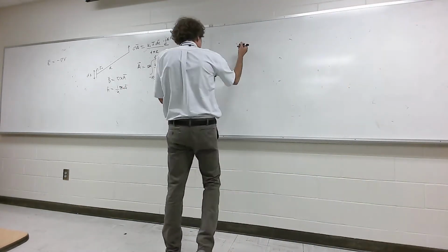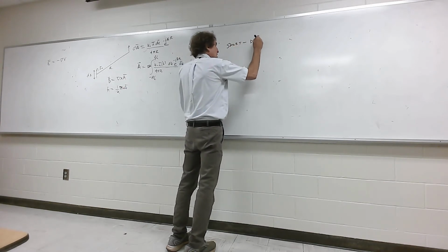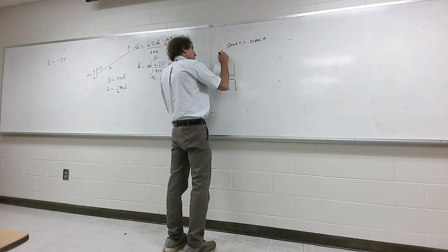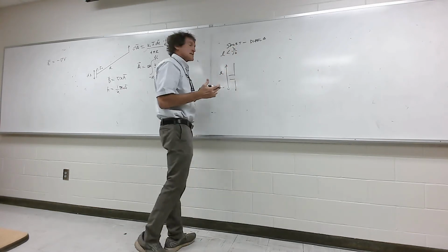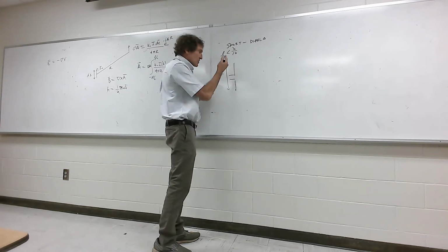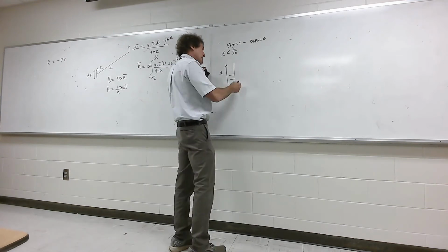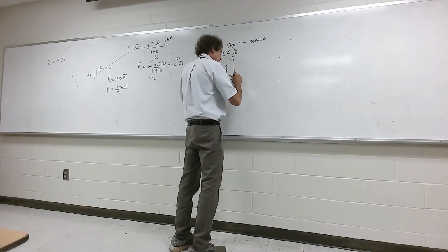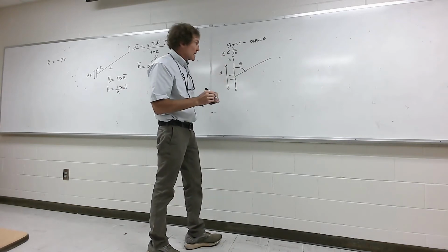All right, so now, pay attention to this. This is the short dipole workup. For a short dipole, it's electrically short. Its total length is L, but L is going to be assumed less than lambda over 10. So it's less than a tenth of a wavelength long. On this thing, we're going to assume the current is uniform in magnitude. It doesn't have any kind of gradient spatially. The vertical axis, we'll call the z-axis right there. Then we're going to come out, and this will be the angle theta with respect to the vertical direction.